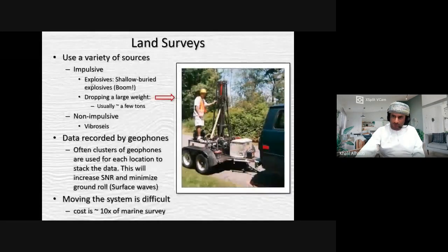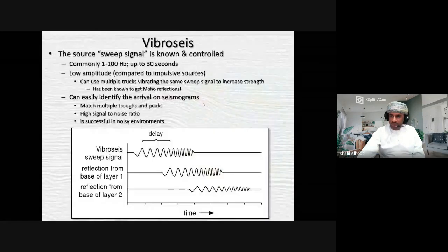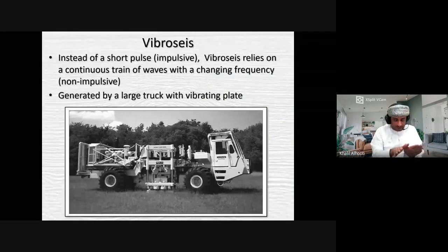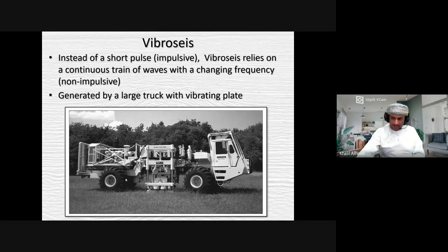If you go back and watch those video links for either marine or land surveys, you'll see what they do. At the time they send the energy to the ground, either the front tires or back tires are lifted from the ground to put more weight on this equipment, on the Vibroseis. There is good coupling then. The coupling between the ground and this plate, the plate you see here, is perfect. Then the energy is sent to the ground.